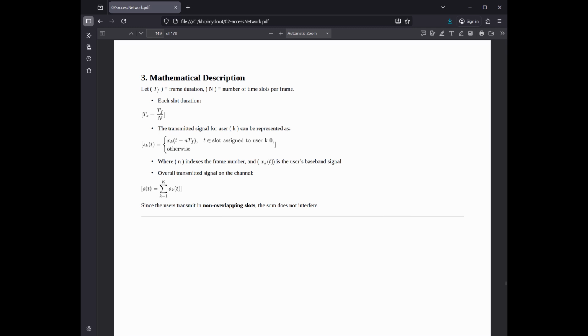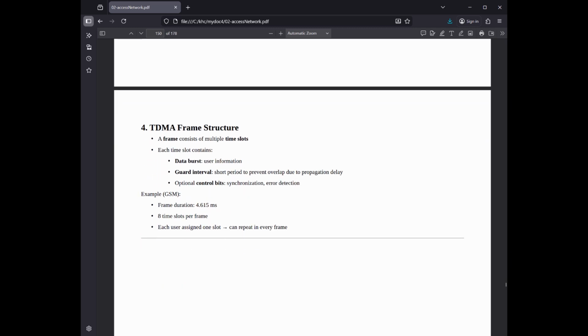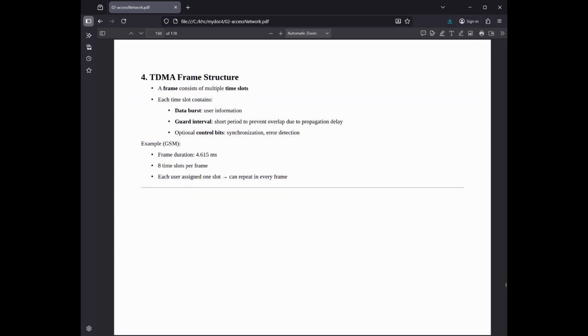where, number of time slots per radio channel. Total available spectrum. Guard bands at the edges of the spectrum. Bandwidth of a single radio channel. Efficiency: TDMA efficiency is the ratio of data bits to the total bits transmitted, including overhead bits, preamble, guard time, synchronization. 4. Frame structure: a typical TDMA frame, like in GSM, consists of 8 time slots.